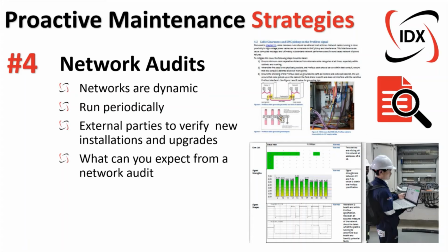What you should expect from a network audit. Well, during our PROFIBUS Engineers course, we do touch on the topic of how to effectively do network audits, and obviously I would suggest taking a bunch of experiential learning from having a professional on site show you how the audit procedure is done. But basically a visual inspection, make sure that all the cables are run in the correct cable category separation. So I'm removing my PROFIBUS cable from any noisy devices or cables. The wiring, the good wiring of all the PROFIBUS connectors, and that device lists and network diagrams are up to date.